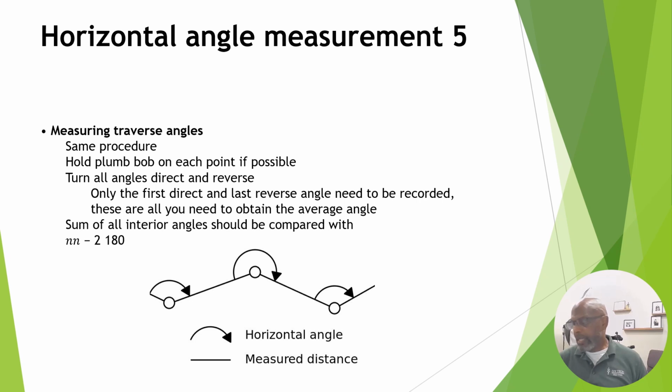This information is used to determine mapping work and to establish grid systems on large construction projects, among many other things. Now, again, the grid work, like if it's a very large warehouse, because the warehouse is so large, they would put a grid in the prints to know where every beam was going to go, and they give it a special number so you know where it needs to be set.